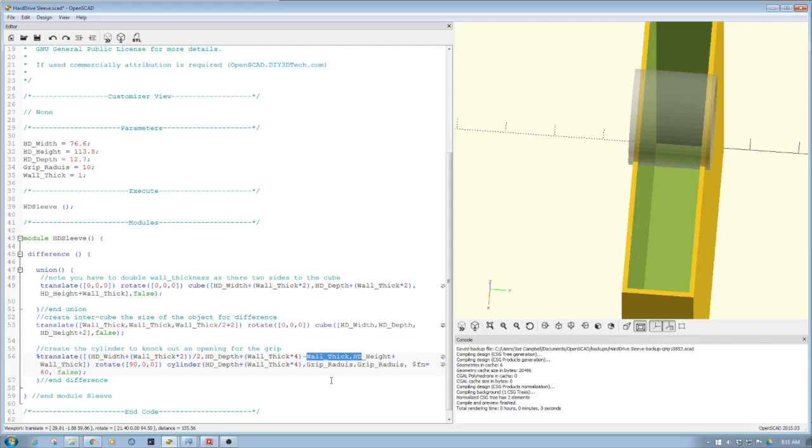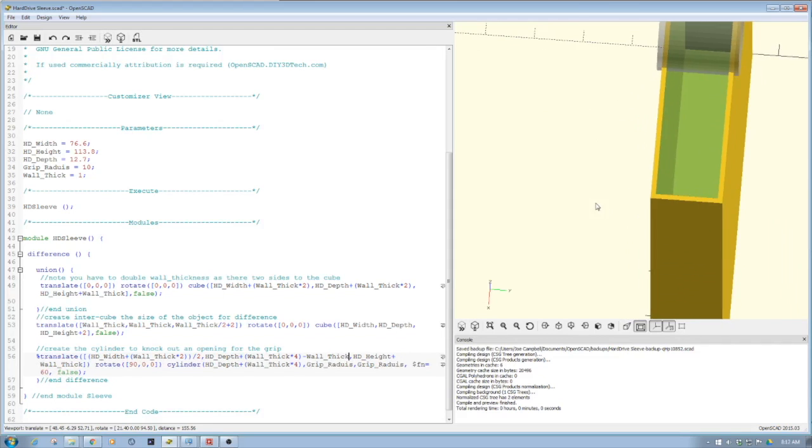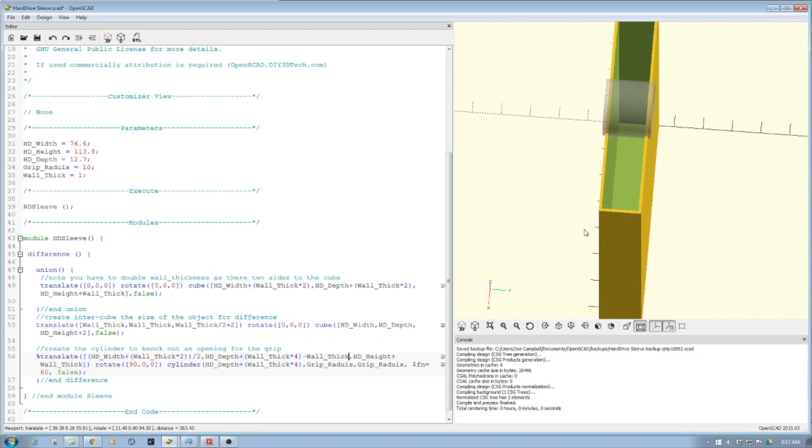This is where it got a little bit wonky for me, because I'm so used to dealing with center, where I split the difference. You don't split the difference in false, so I had to back off one of the wall thicknesses to maintain the center. If I were to remove this, you see how this now moved off center. So no matter what I do, I cannot get that center unless I go back and remove that singular wall thickness, because I am offset from my origin because of the false. Whew. I hope that made sense.